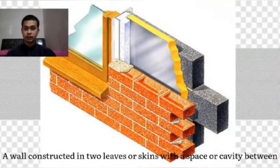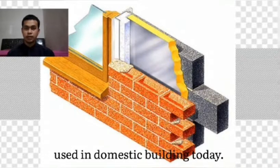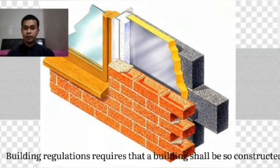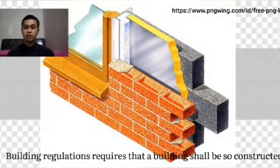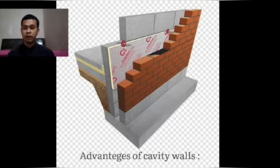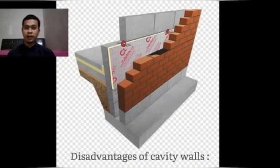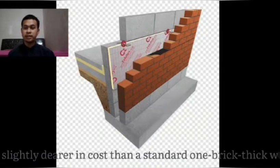A wall constructed in two leaves or skins with a space or cavity between them is called a cavity wall, and it is the most common form of external wall used in domestic building today. Building regulations require that buildings shall be so constructed that the combined depth, insulation, and wind resistance of cavity walls need no external rendering. A disadvantage of cavity walls is that they are slightly higher in cost than a standard one brick thick wall.